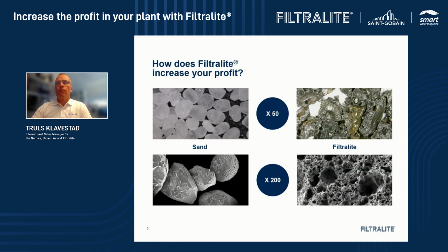So if you have 1 cubic meter available, you can store much more suspended solids in 1 cubic meter with Filtralite compared to 1 cubic meter with sand, due to the properties of Filtralite.